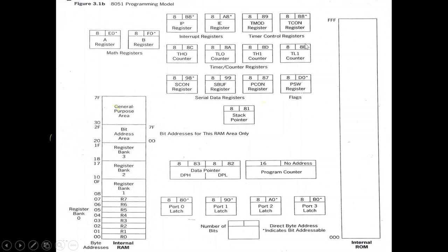So for each and every byte, we can see how it gets those values, and we can see it while going inside the program also. We can see how this memory address changes, because all of these are given specific memory addresses. That is the advantage of the 8051. Each and every register is given an individual address, so I can directly give TH0, or I can give that memory location and give the values directly.